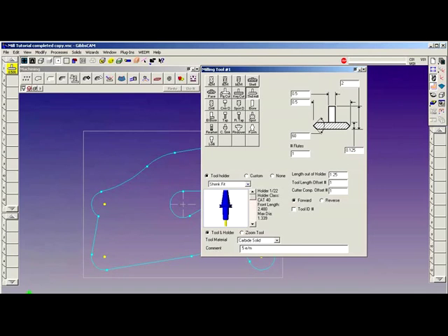If I was cutting a 1/4 20 thread, same approach. 1 divided by 20 equals 50 thousandths. Doing it in this manner ensures that we get a good representation when we render the thread.